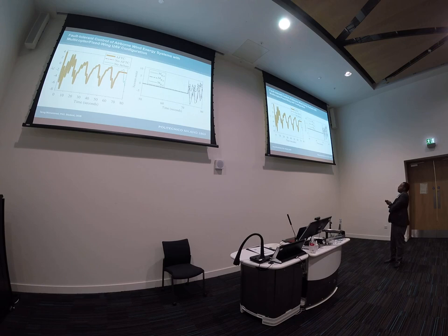Everything is normal. This is the rudder deflection. And at the second 17, we injected a failure to the rudder. The rudder is the most used discrete surface in loop. In normal operation, the rudder will act like this, in the green line. But the failure mode is just that we fix it at 0.